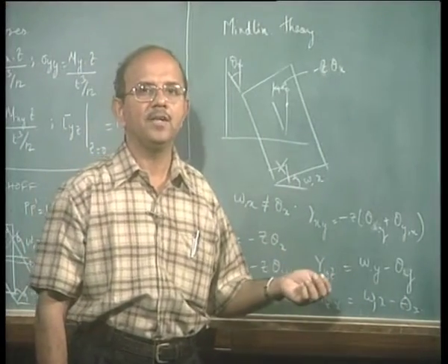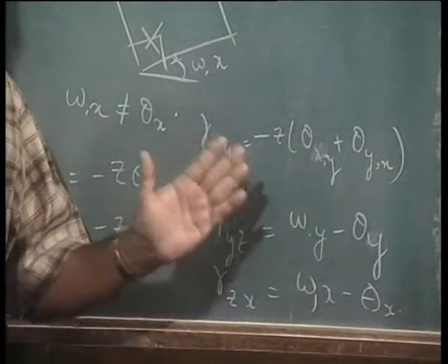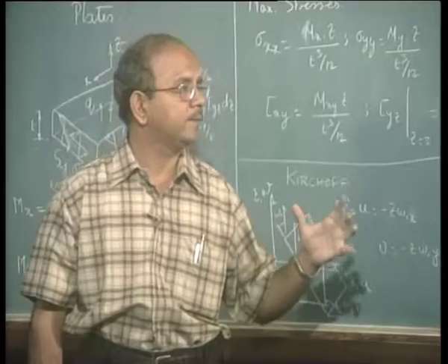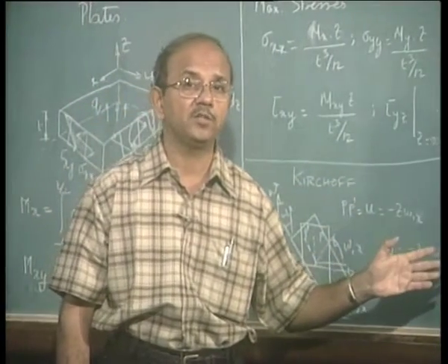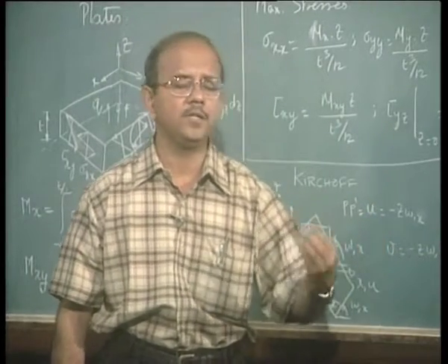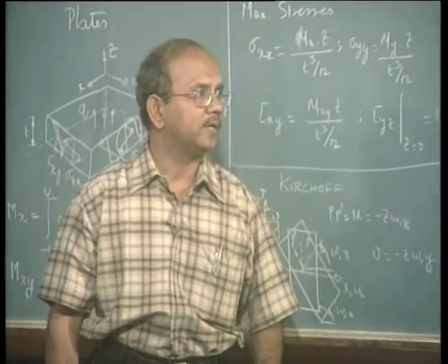But ironically, many elements, when the plate becomes thinner, may not give as good a result as some of the elements which are developed on Kirchhoff theory. Hence, many software packages may have different element formulations, one set taking into account shear deformation, another set which may not take into account shear deformation. But it's a good idea to have some idea of the thickness, and then use the elements appropriately.